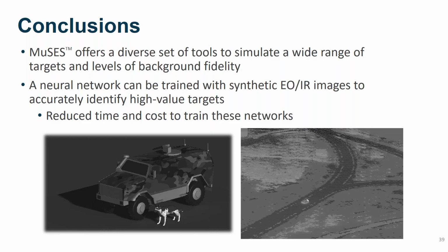Okay, thank you. I didn't think MuSES had capability over the visibility band, but I saw reference in the presentation to the visible band. Does MuSES actually have predictive capability in the visibility band? Yeah, so MuSES can render in the visible band, but it's a radiance image, or like a grayscale prediction. We don't do a true color visible prediction. So we can predict radiance in the visible band, but we don't do a true color image prediction.